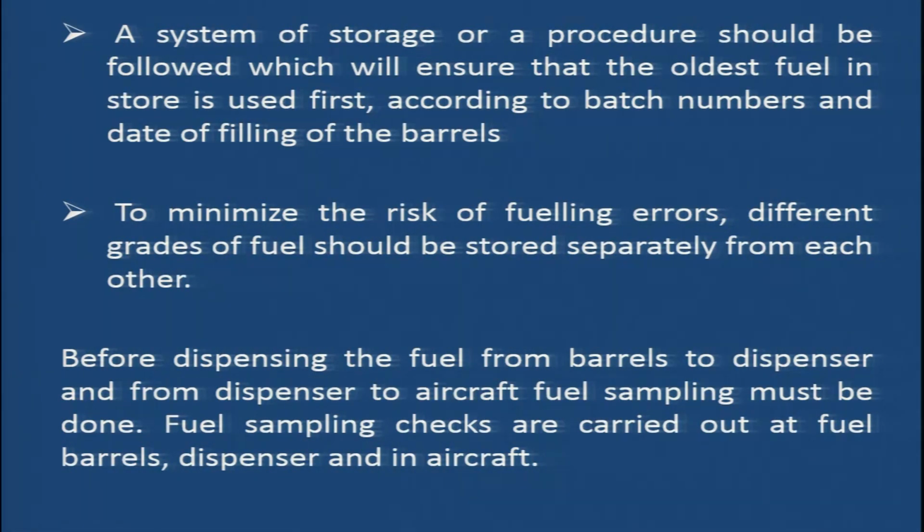To minimize the risk of fueling errors, different grades of fuel should be stored separately from each other. So, it is always advisable to store different grades of fuel at different places, so that we do not mix up with the wrong type of fuel.